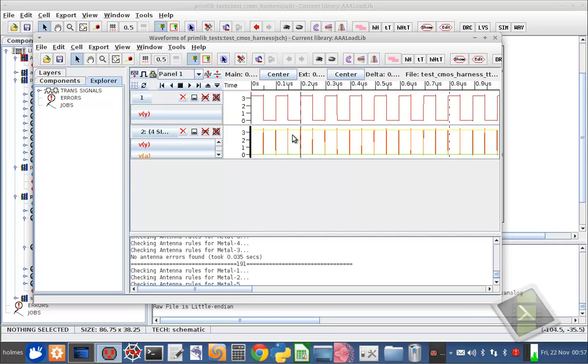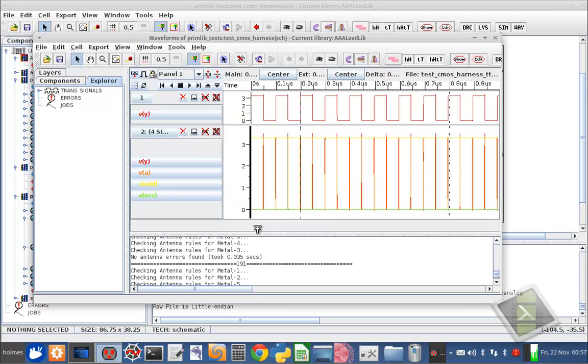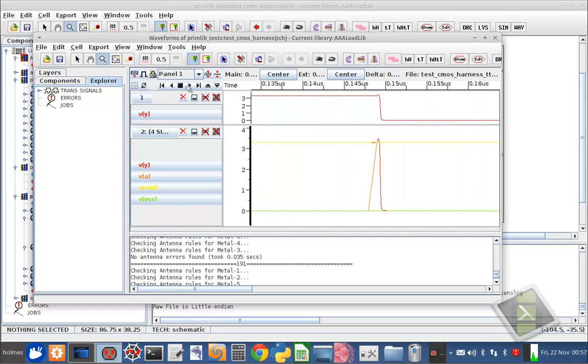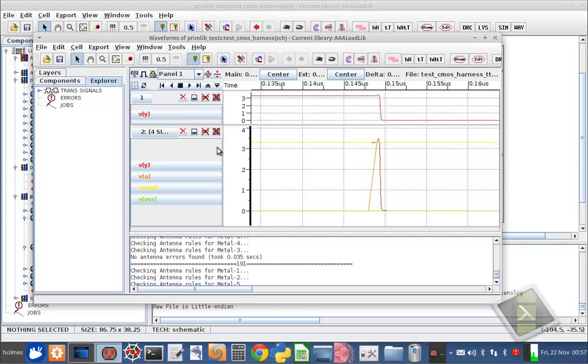And I can zoom in on the signals. Take a look at how they look close up. There are different things you can do in the electric waveform viewer. You can set some grid axis, and there are some measurement tools in here as well. You can use the measurement tool to look at voltage and time differences. It's got some handy tools in there, they're very good.